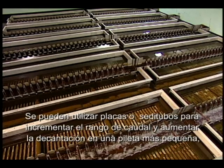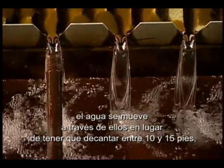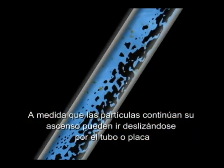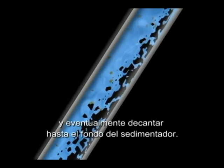Plates and tubes may also be used to increase flow rates and enhance settling in a smaller basin. As water travels up through them, instead of having to settle as much as 10 or 15 feet, particles have to settle only a matter of inches to reach the surface of a plate or tube. As particles continue to settle out and build up, they can slough down the tube or plate and eventually settle to the bottom of the basin.